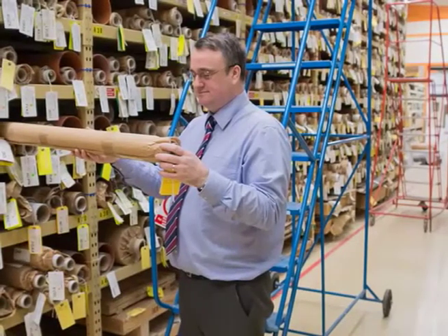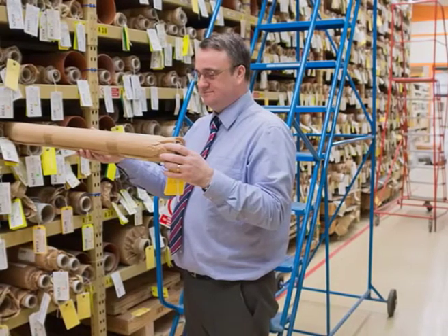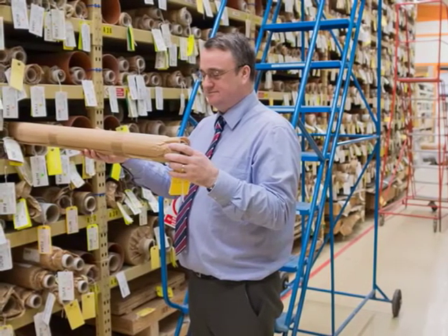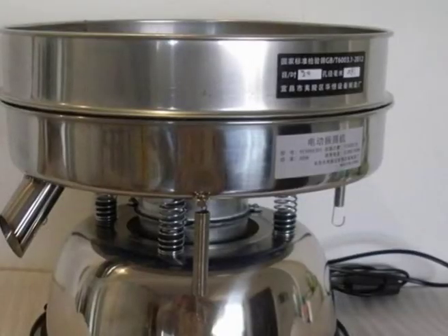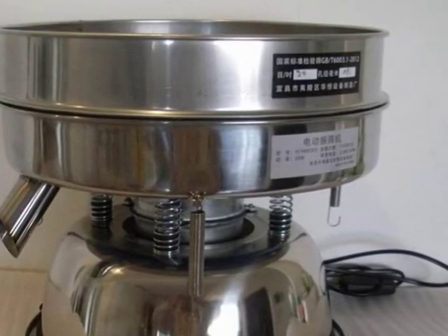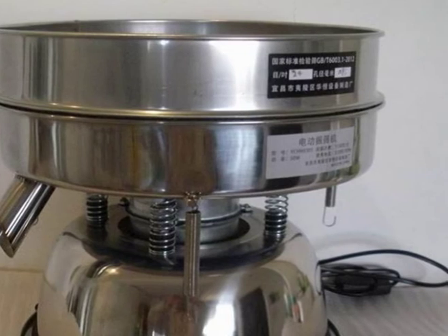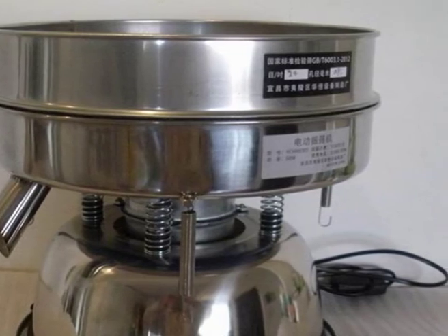Pharmacists should ensure that sieves and screens are intact before and after the processing. When any new sieve is received, the mesh size is checked against the sieve number punched on the edges of the sieve. Pharmacists should personally monitor all the critical operations like dry mixing, addition of binder, wet mixing, drying inlet and outlet temperature, mixing time during lubrication, machine setting, in-process parameters, etc.